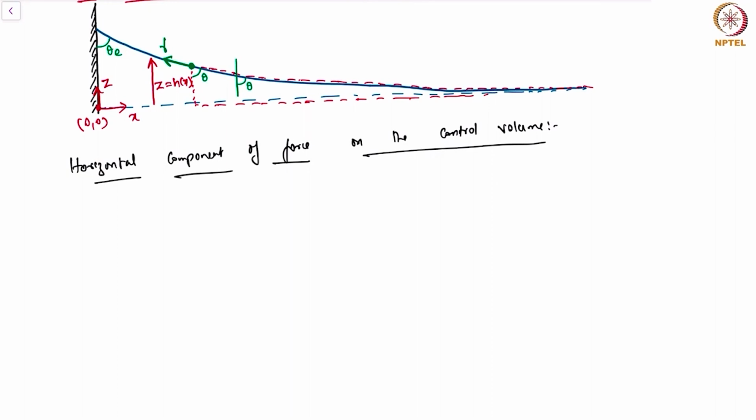surface tension gamma, the local angle is theta. The horizontal component of the surface tension force on the meniscus would be minus gamma sine theta over here, but on the other end the meniscus is flat and therefore I have a gamma on the other hand.